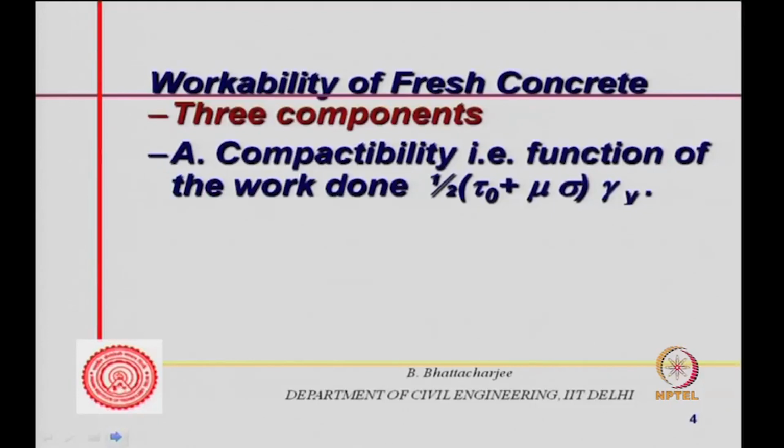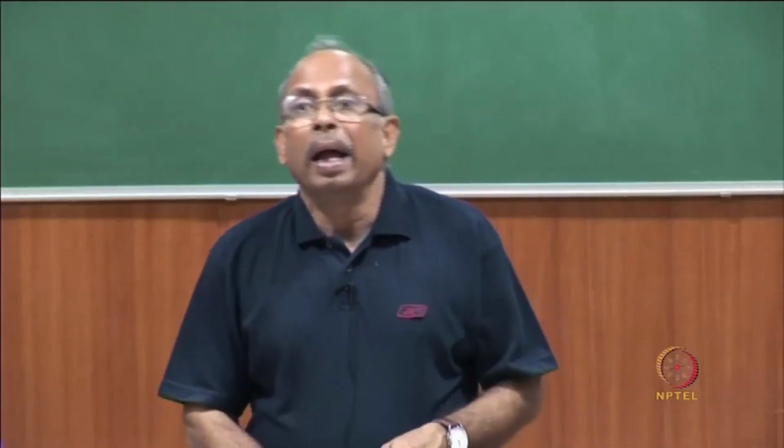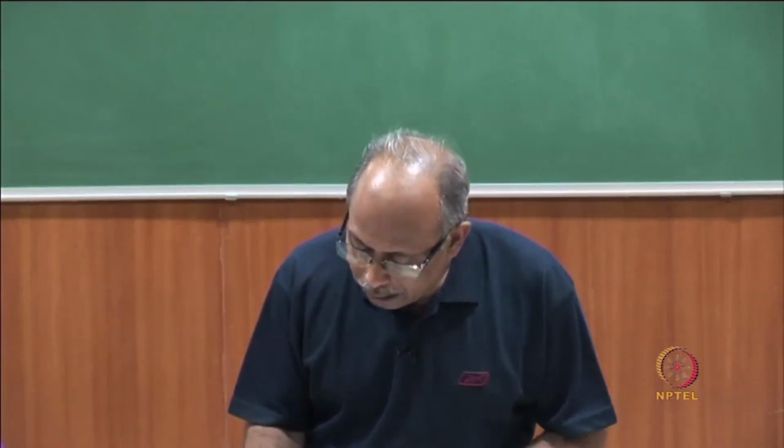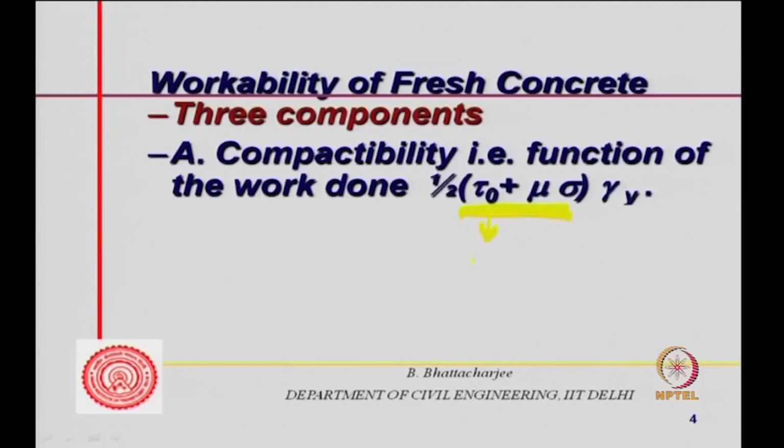If you recall the rheology of concrete which we talked about, we talked about yield shear stress, beyond which I have some viscosity. Therefore, the stress at any point will be given by this yield shear stress plus the coefficient of viscosity, and a function of normal force, like soil.